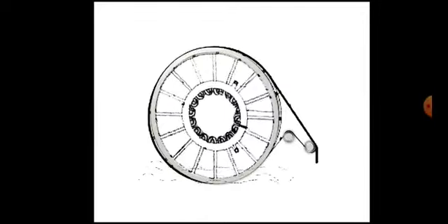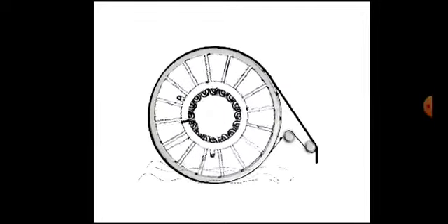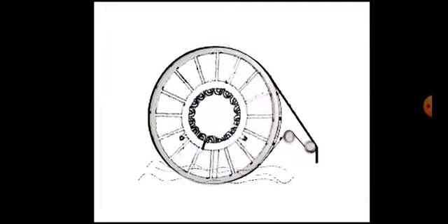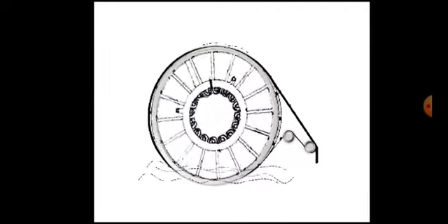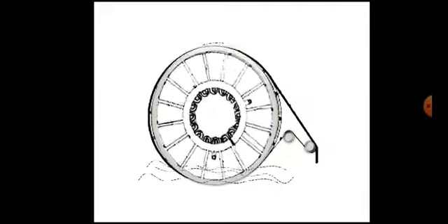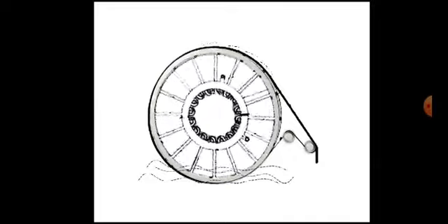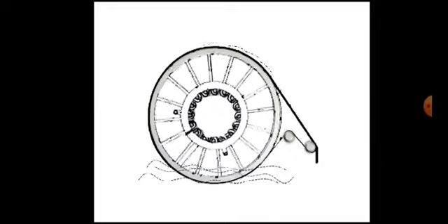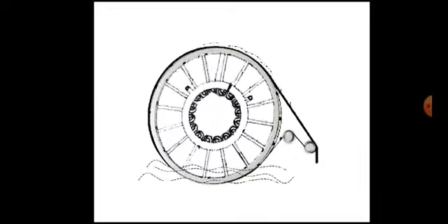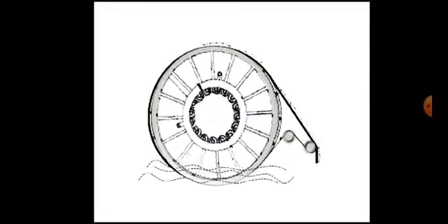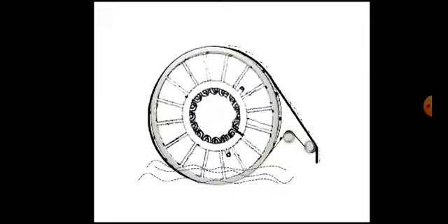The rotating drum at the bottom has a broth to be filtered, and this is how the insoluble material remains outside and forms the filter cake, and this filter cake is being discharged using this string like this.